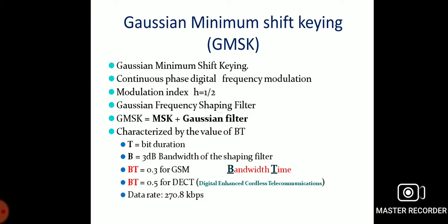In this modulation, the non-return to zero waveform goes through the pre-modulation pulse shaping filter with a Gaussian response. The output is obtained with reduced side lobes in the transmitter spectrum. The GMSK signal can be coherently or non-coherently detected, like phase shift keying.